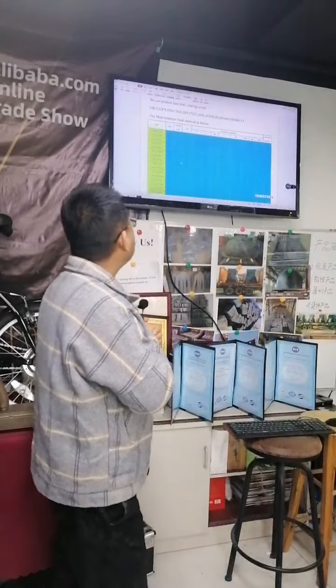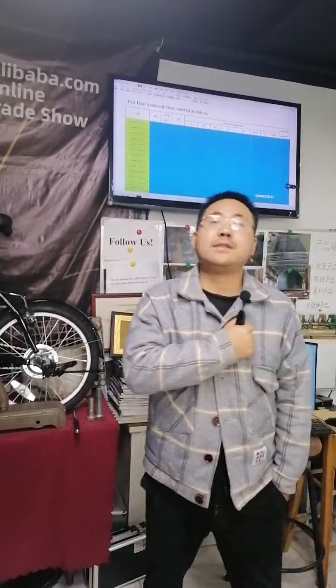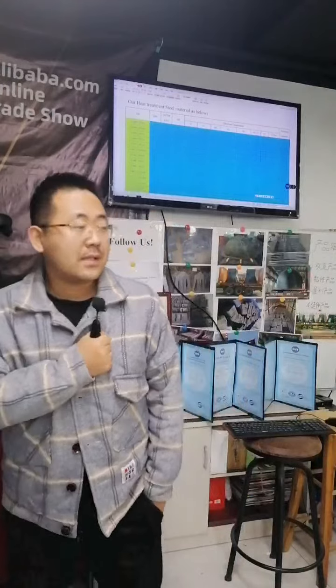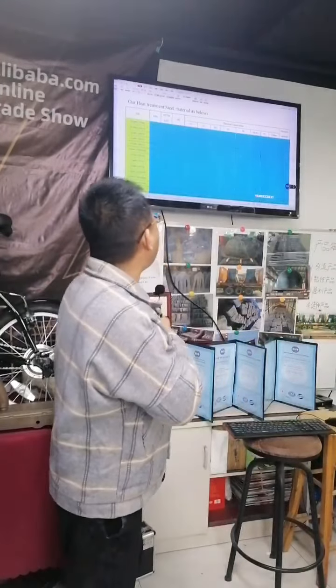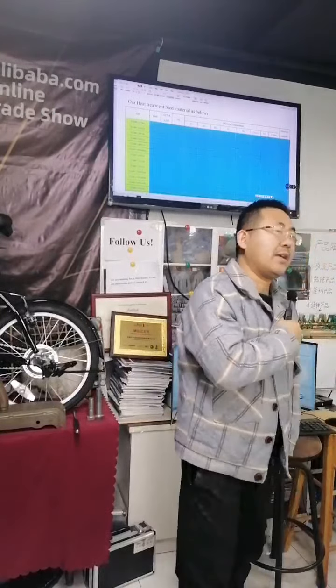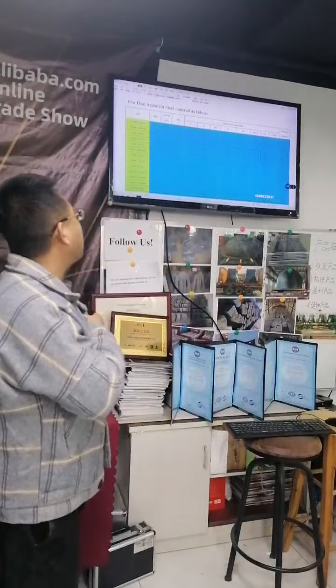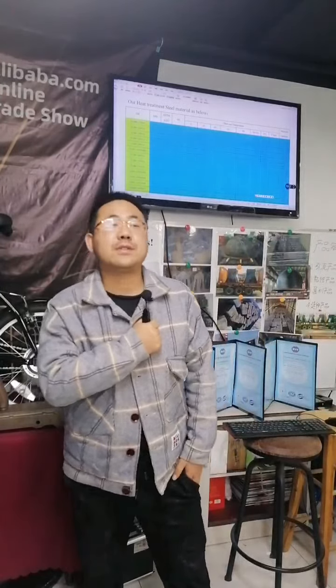And our other material is 1.4837. This material is ZG25Cr25Ni20. We also call it ASTM 297HH, and that includes 25 chrome and 20 nickel.